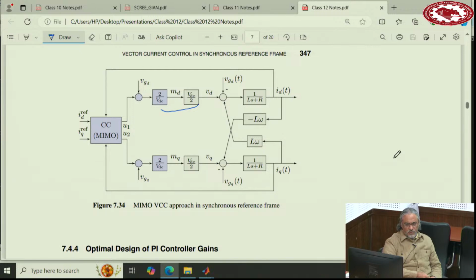See, when you have harmonics, for instance, in the grid voltage, and you want to prevent them from going to the grid current, then, as we discussed, through that transfer function that we showed, they will go to the current anyway, so you have to stop them. And then we put resonant controllers at that particular harmonic, 5 for instance, or harmonic 7. So if you really want to remove one harmonic completely, you need to put a resonant controller for it. But this is not really practical if you have many harmonics and you want to remove all of them.